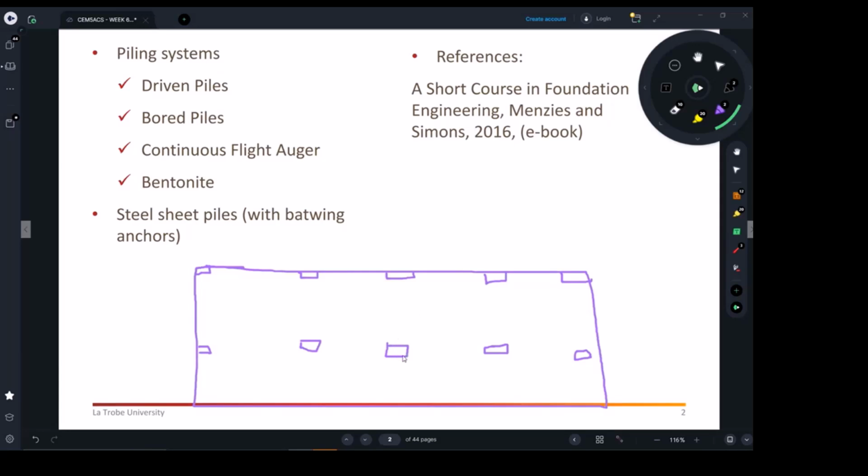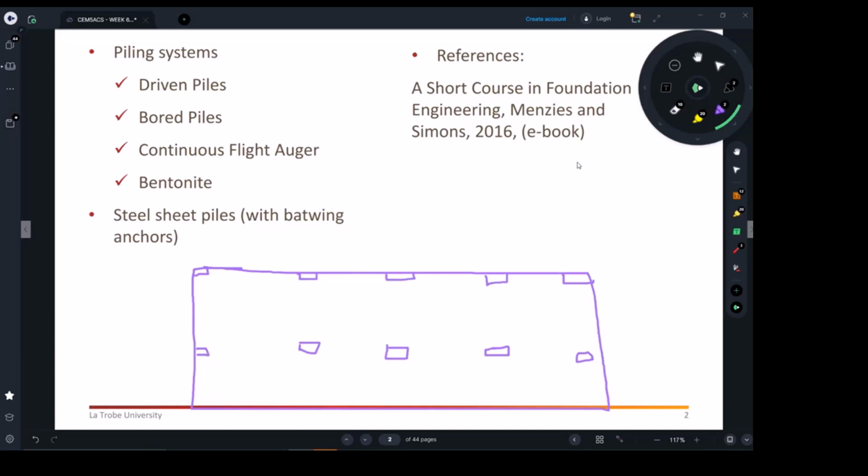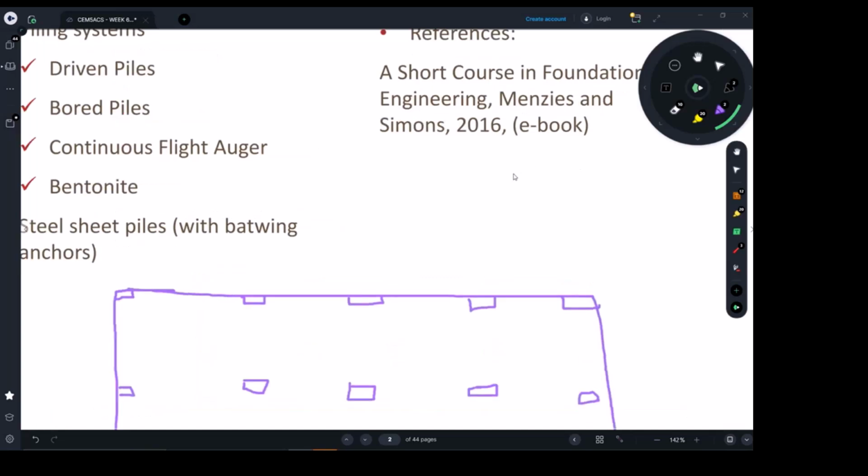Usually, if you have a short building, like a 5-story building, like what I shared with you with the school, you're simply going to have your column sitting on a pad footing, and that's it. The bearing capacity under the pad footing was good enough to carry the load above. Done. But when we're talking about high-rise building towers, usually the bearing capacity under the pad footings is not enough to carry them. So what we do, we put piles.